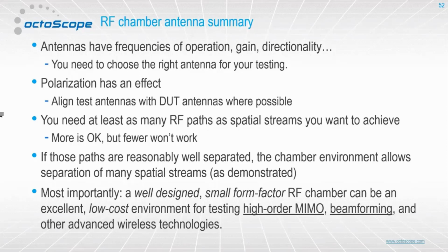There is a feature called antenna diversity. So for choosing the right antenna, do we have this feature tested? Antenna diversity usually refers to the fact that, let's say on the AP side, the receiver itself will be getting signals on all of the antennas, and the receiver can choose how it wants to use those antennas.